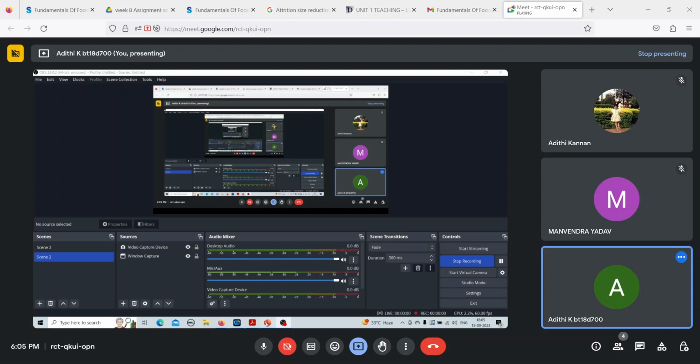That into sieve stage is what is done here. So fraction of the weight retained into sieve stage. Sieve stage is 4, into fraction of weight retained, which is 10 by 110. If you do this, we get a value of 0.3636.